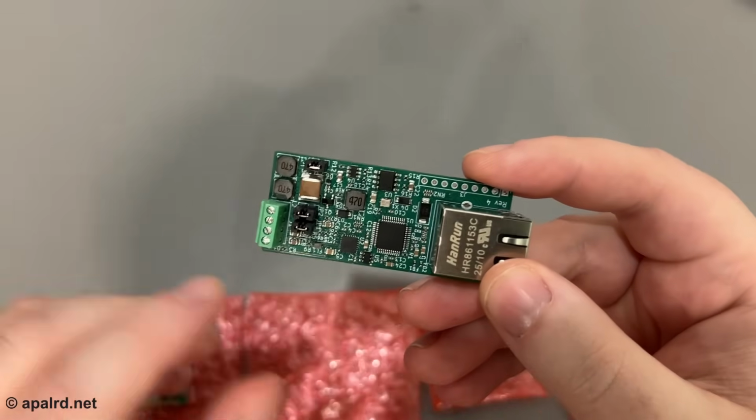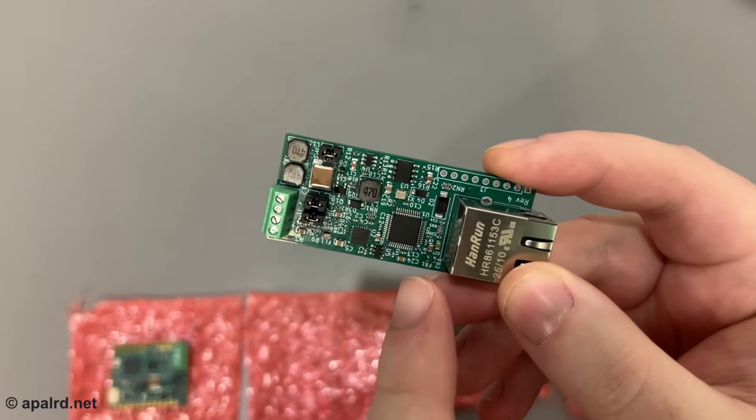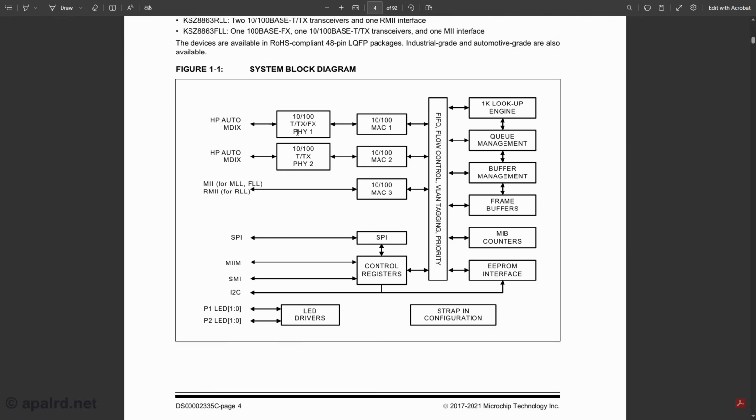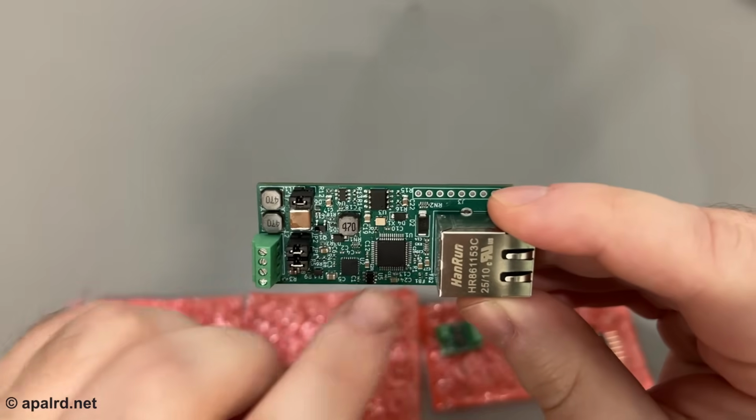As for the architecture of this board, he's got the T1S Phi, and then this guy here is a small switch chip. So it has integral 10/100 Ethernet on this side, and there's a small microcontroller that just boots up and configures these chips so they pass traffic.